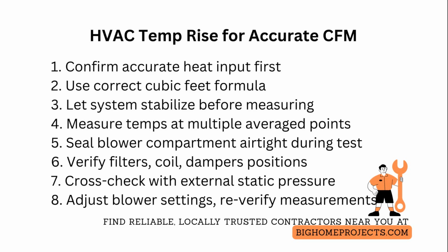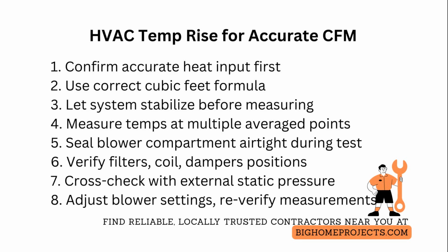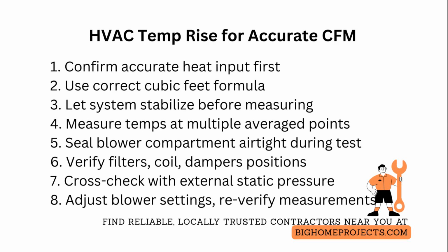Shield the blower motor compartment during testing with a tight cover so the blower does not pull room air, which artificially lowers temperature rise and inflates calculated cubic feet per minute. Use cardboard, sheet metal, tape, and magnets to make it airtight.